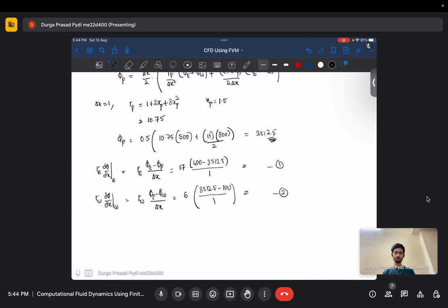Yeah. So I'm just wondering why you are saying this diffusion coefficient, gamma times dou phi by dou x, is a flux. This is essentially the heat flux. If phi is your temperature and gamma is your thermal conductivity, that will be your heat flux. And the divergence of that is the net change, right? Yes. Yeah, so we're coming from the heat equation. Awesome. So we're looking at flux of temperature.